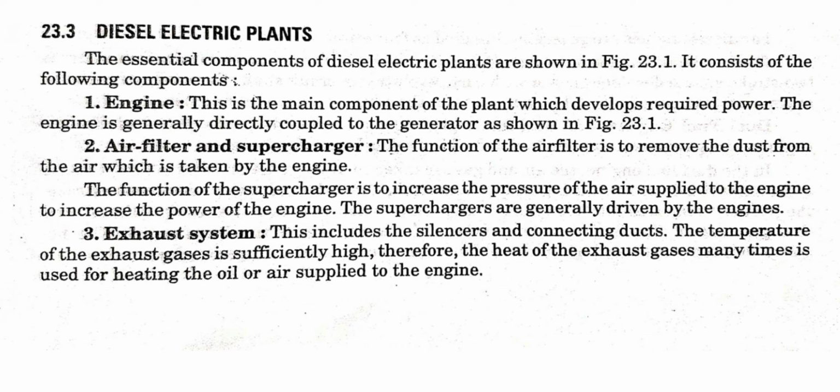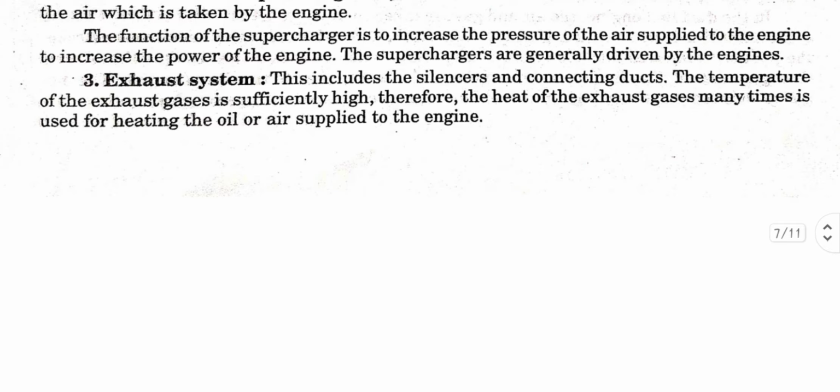Third component is the exhaust system. This includes the silencers and connecting ducts. The temperature of the exhaust gases is sufficiently high. Therefore, the heat of the exhaust gases many times is used for heating the oil or air supply to the engine.